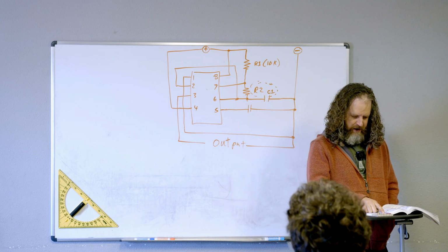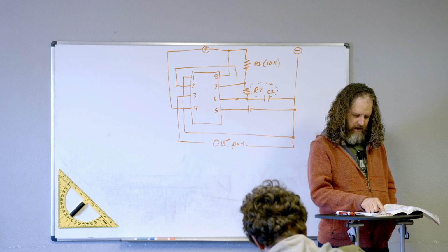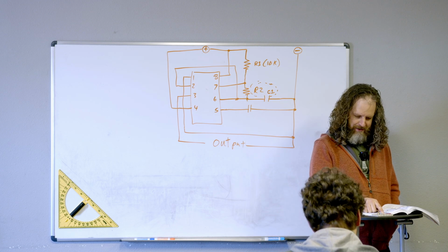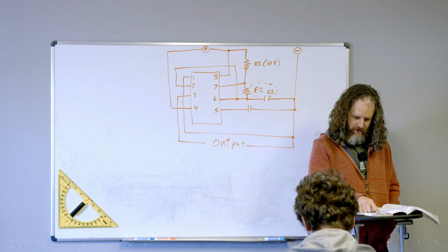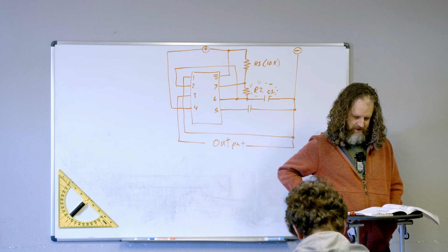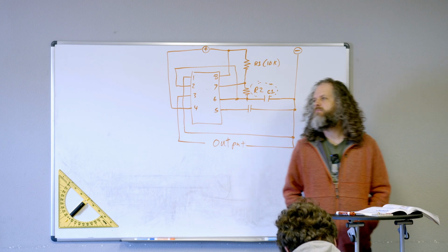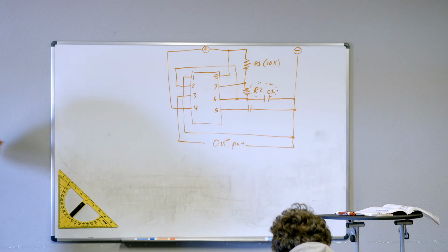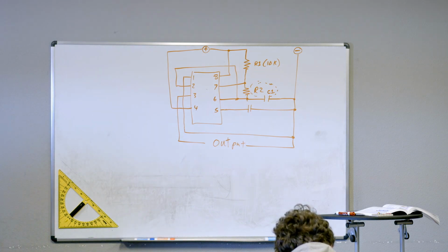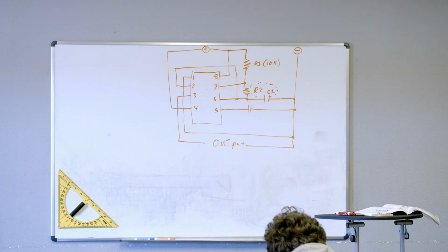At 10 microfarads, between a 10K and 1 megaohm resistor, you can get 4.82 hertz, 2.7 hertz, 1.4 hertz, 0.69 hertz. What is this pointing to? So this always goes to ground, and this gets where you want to probe, so it'd be at the LED.